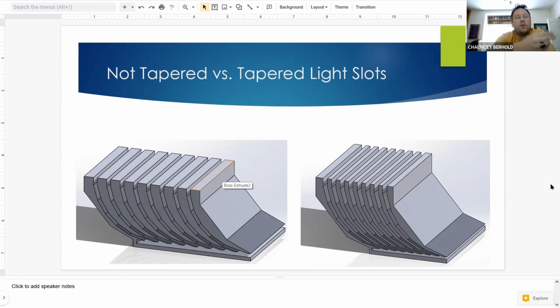And as you can see, and as we've talked about before, the light goes through the CPCs, which I excluded to be able to make this portion look more clear, and then is reflected down into the bottom, to the common light channel. And these can be stacked next to each other so that it truly is a common channel going all the way to the end of that array, where it effectively dead ends into light guides, which we'll be using fiber optic light guides as they're the most common and the cheapest.